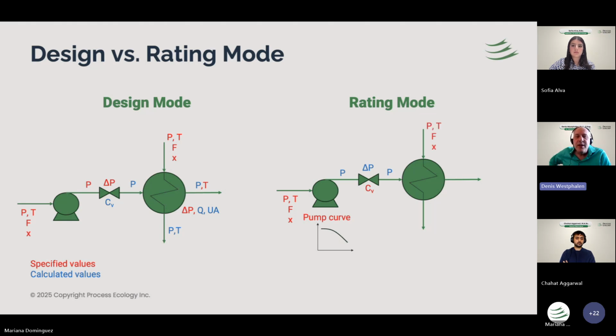Comes to the heat exchanger. So let's say that on one side, on the other side, we have the inlet conditions known. Then our specification is not the outlet temperature, but rather the UA factor. Or sometimes we go further and go all the way to a rigorous calculation, so we can embed an EDR, Aspen EDR, or the HTI. So when you have access to those engines, you can run the rigorous thermohydraulic calculations for the exchanger, and then you would get the outlet conditions specified.